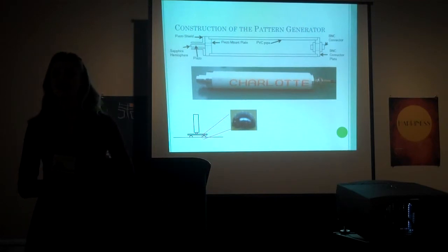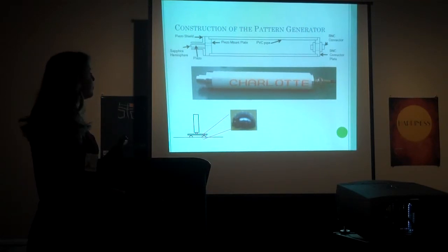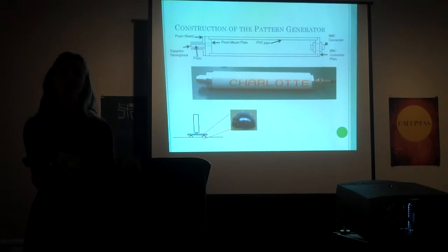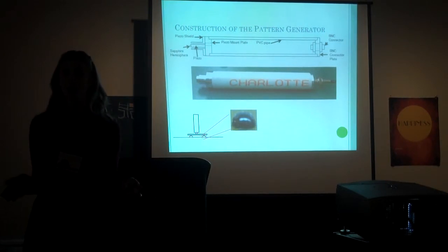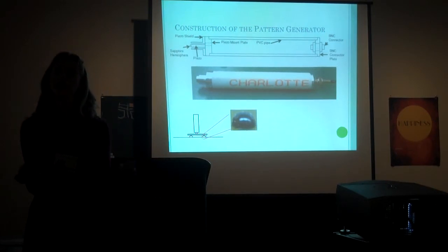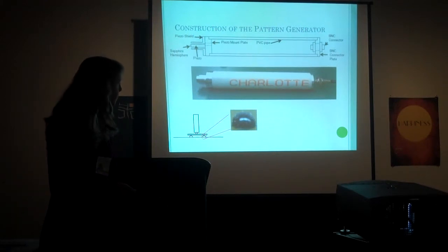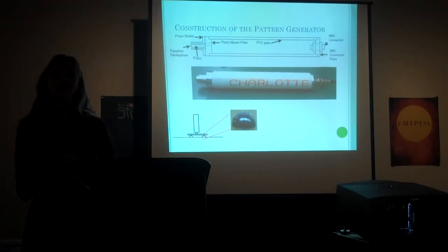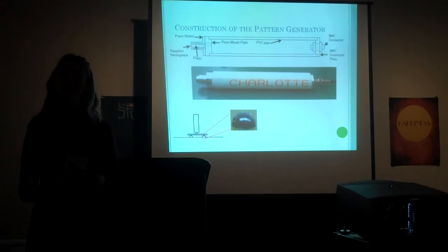So we took our best guess, and we came up with these bumpers that are hemispheres, so you have the smallest contact area of the plate as possible. Because if it's too large of an area, it will damp out the vibrations, and you will not form these patterns anymore. We have tried 3 different stiffnesses: extra soft, soft, and medium soft.